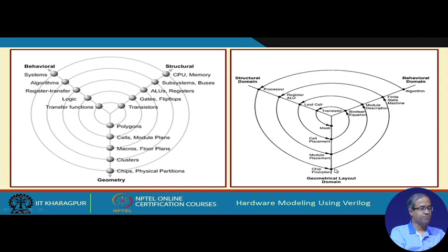which you translate into a chip floor plan, and each of the blocks in a chip floor plan you translate into finite state machines. They will be translated into registers and ALUs, they will be translated at the physical level into modules, which will be placed, module placement. Then each of these modules will be having a description at the behavior level, module description. Now, each of the modules will be designed as a netlist, we call them as leaf cell, they will be placed, cell placement. Now, each of the cell will be expressed as Boolean expressions, they will be realized using transistors, and finally, they will be realized using the layout masks.